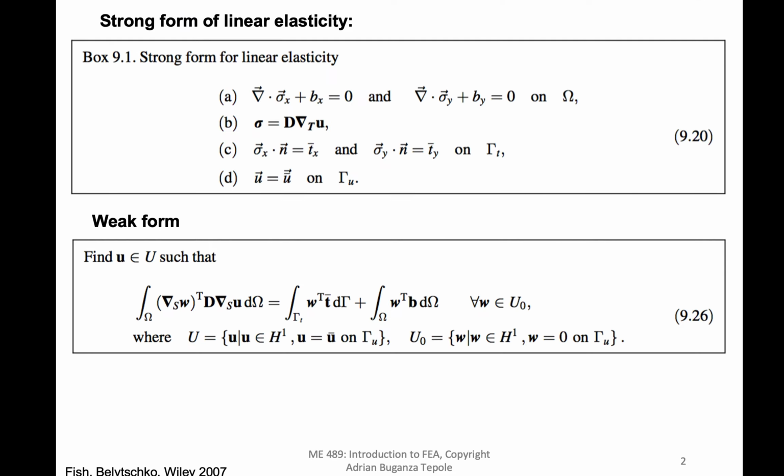down. So the first thing, just as a reminder, the strong form of linear elasticity is this force balance, and then we have the weak form, and this is what we solve with the finite element mesh.